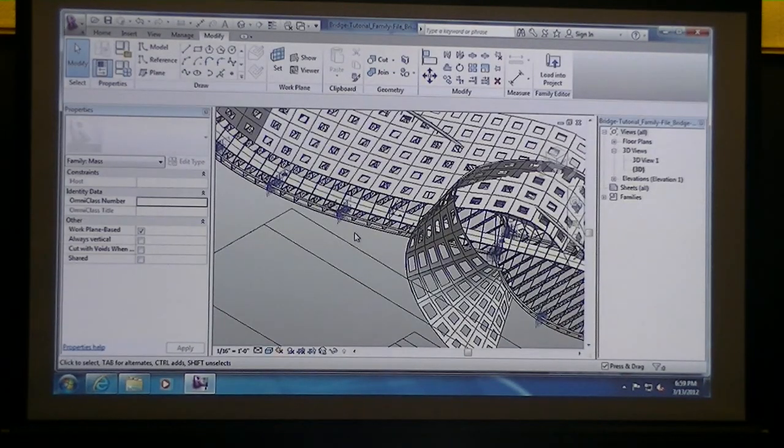Remember, I also sent you an email saying I tried to do some nice cool tectonic railings, and I applied it to my bridge, and it turned out really cool. It was making my rendering go over an hour, and then I looked at my file size, and it was like 200 megs just for putting in this repetitive curtain wall panel. So I was basically saying don't worry about getting to that level of detail.